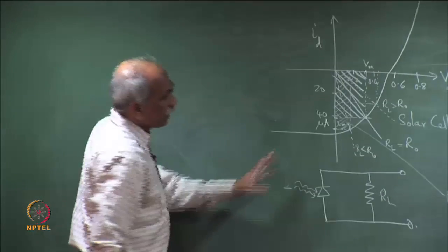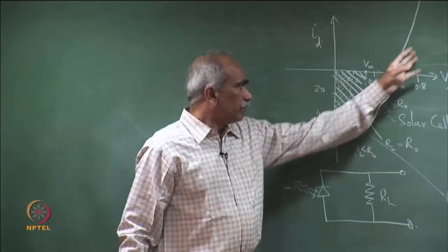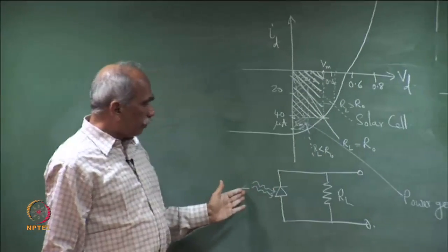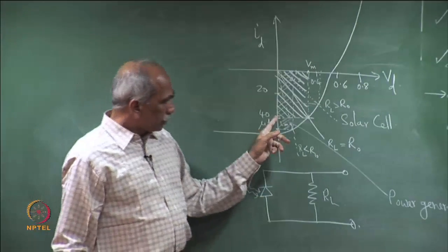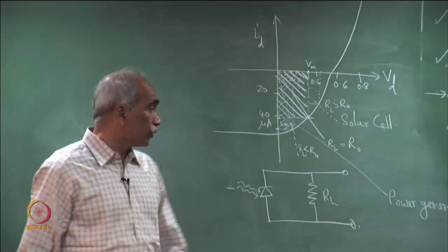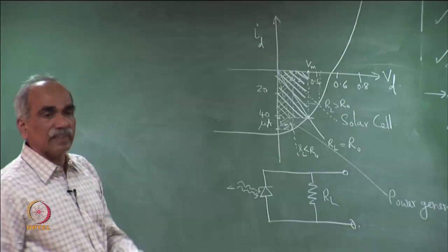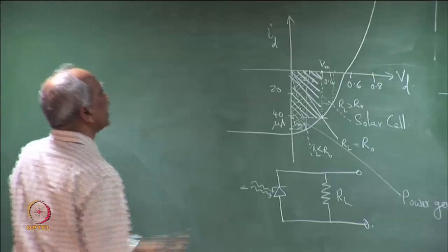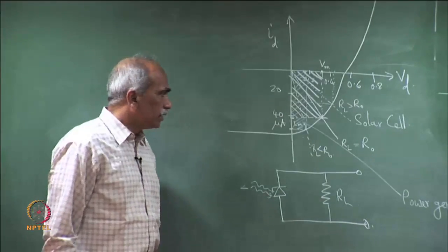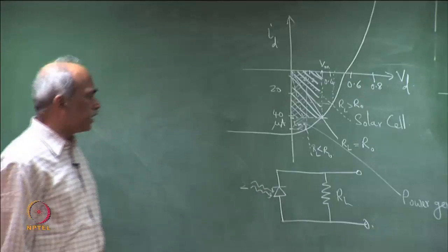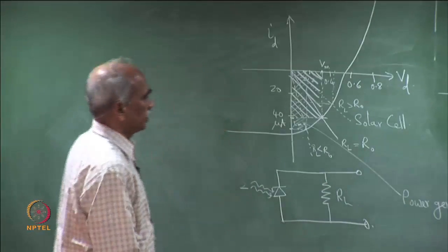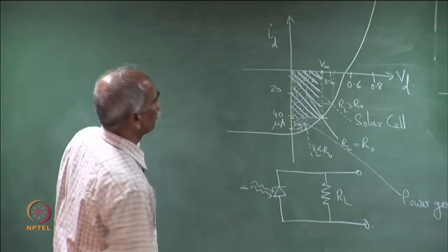So, a solar cell is basically a photodiode which is operated in the fourth quadrant and without any bias. So, an important issue is the choice of the load resistance from a circuit designer's point of view. The materials issues are completely different. So, this is from a circuit designer's point of view, to get maximum power out of this.